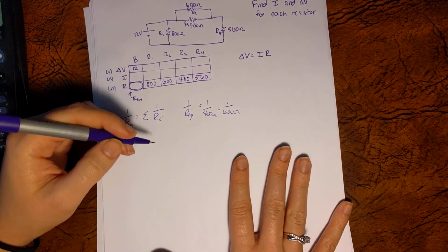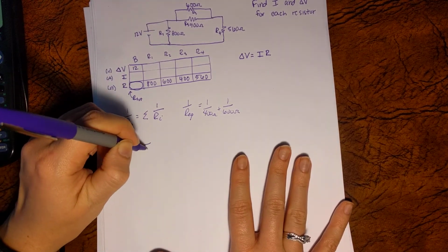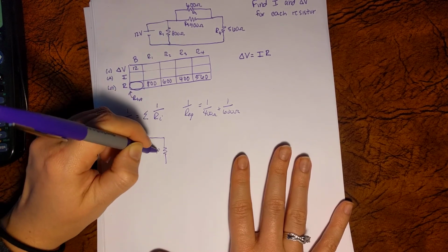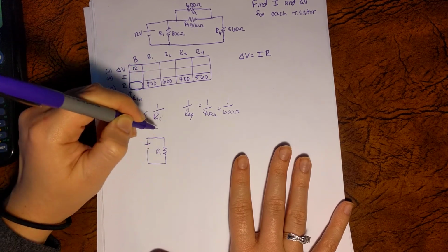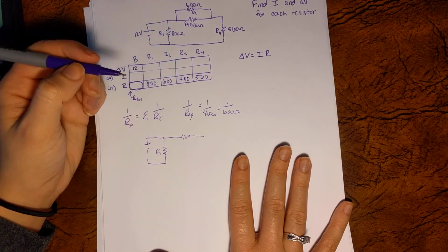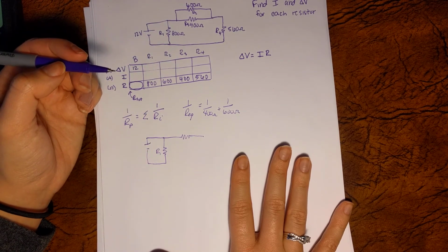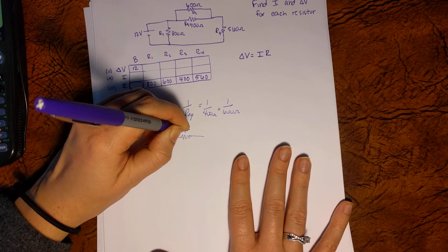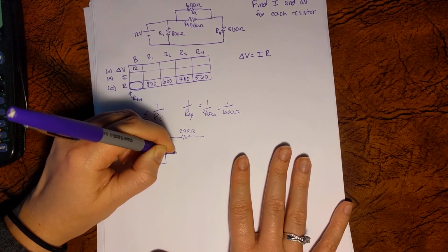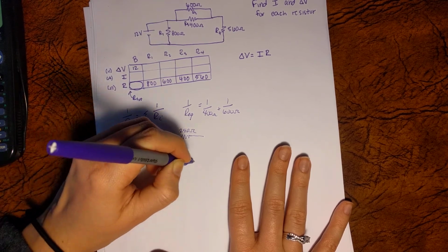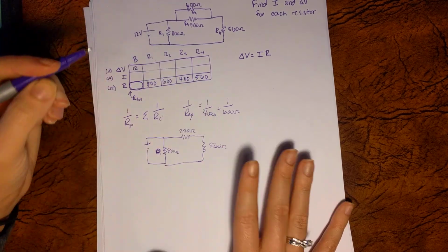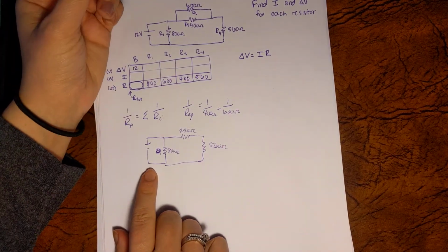So I'm going to redraw my circuit to show that simplification we've made. All right, so now we've got our battery. We still have R1 going on here. But now we've got one resistor here, which is now 240 ohms. Actually, instead of R, I'm going to write the exact value since here we're just simplifying. And this is 560 ohm. Well, now this is better here.